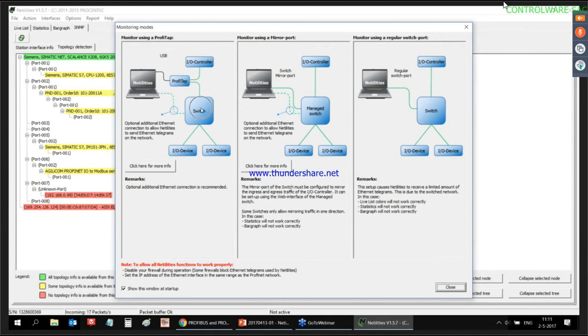Why do you need to have two Ethernet ports? Well, the Profinet is analyzing the Profinet data, so it is reading the messages that are sent from the controller to the switch, but it is not capable of sending any data over the network. This is because it's a protection, a barrier if you don't want to interfere in your network.